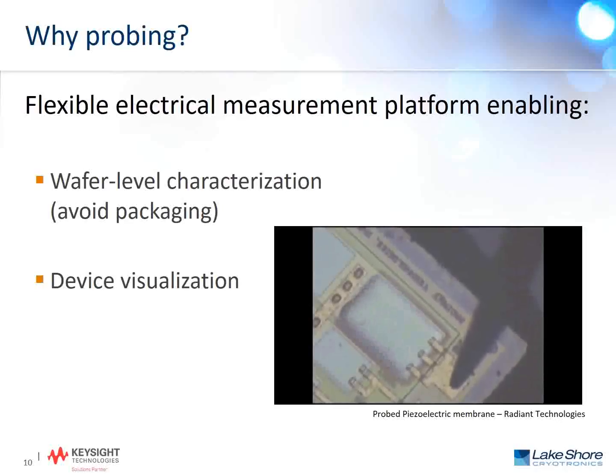Here in this slide, I'm showing a probed PZT membrane, which is flexing as the voltage to the device is modulated. Because we could see this device under operation, we're able to observe clear changes in both the amplitude as well as the structural modes as this device was cooled to cryogenic temperatures.